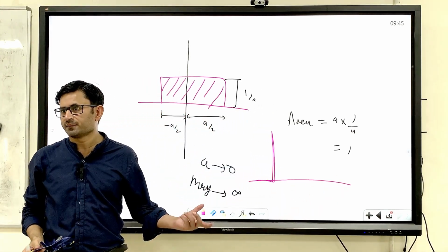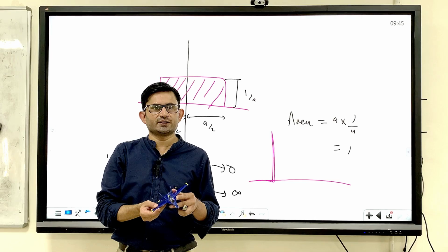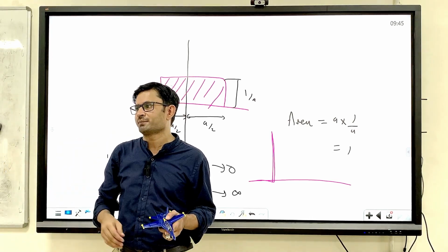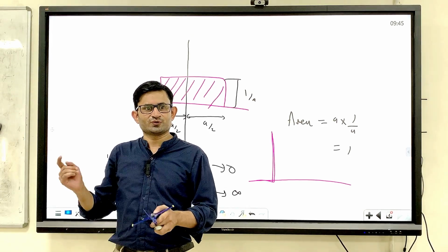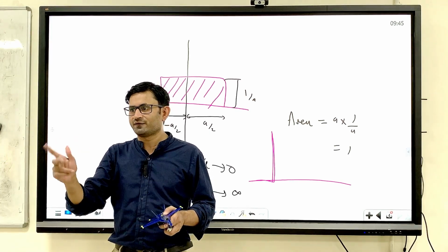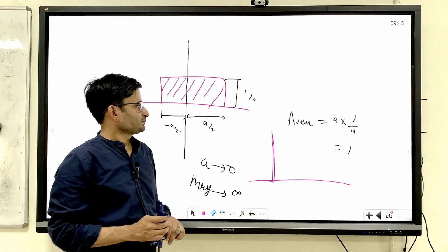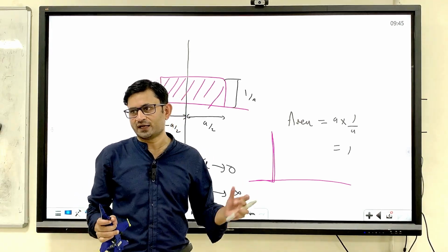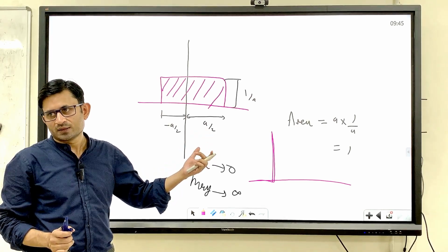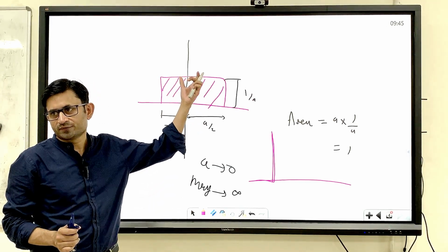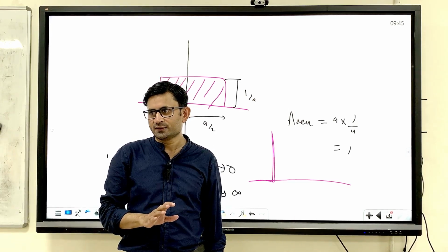Very small interval of time, right? So you have a feel for this. When you roll the aircraft, you generally give the aileron, right? You give the down aileron and then return back to the original position. That is how the aircraft rolls. For elevator and rudder, you can have a feel for step response. For aileron, you have a feel for an impulse response. Impulse is a little confusing, but I have tried to explain with this simple example why it is 1 and why it goes close to 0 and then to infinity. So now unit step, unit ramp and unit impulse are clear.